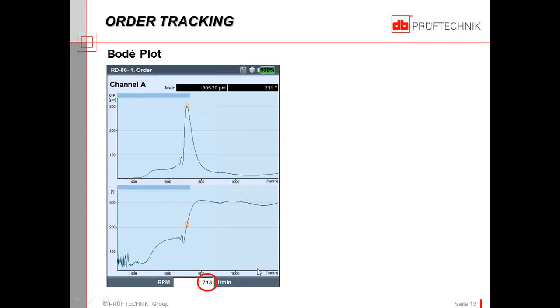Now we have phase versus RPM, and we can see the phase is fairly steady until I start approaching this peak. As we approach that peak, the phase shifts roughly from around 300 degrees to 200 degrees, so about a 90-degree shift at the peak. Then as the vibration amplitude drops down through to slow roll, the phase again shifts another 90 degrees down to the slow roll condition.